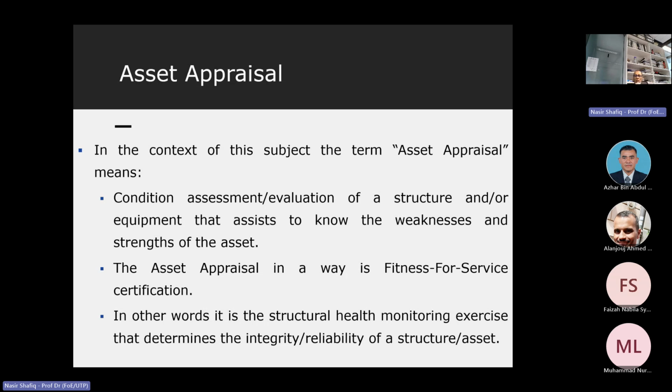From past corrosion data, you can estimate how long it will take for the pipe corrosion to decay the pipe so that you cannot operate more than 100 bar, right? Because of detailed analysis of the data, it will save your inspection, it will save your money.